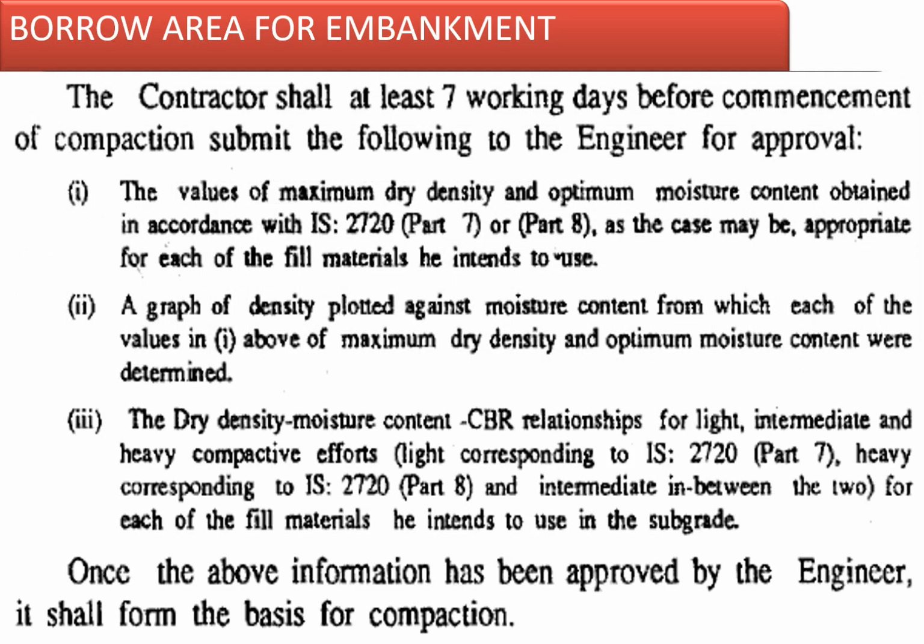Then the compilation of the test results is submitted 7 days before the commencement of the work to the engineers for approval. The documents necessary to submit are basically the density moisture relationship, the maximum dry density and the optimum moisture content of the soils, and then the dry density, moisture content and CBR relationship for light, intermediate or heavy compaction efforts.